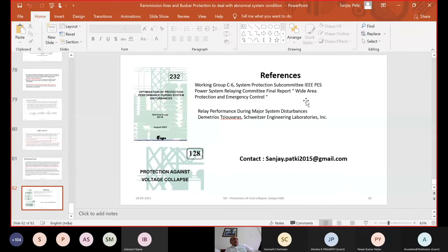The only thing is your earth fault protection in terms of zero sequence. If it is getting transferred from third harmonic or zero sequence from the load side to the HT side, usually if you have a delta winding on the step-down transformer, then it will not get transferred. If you have a star-star winding, then that zero sequence and third harmonic current can get transferred to your main transformer.